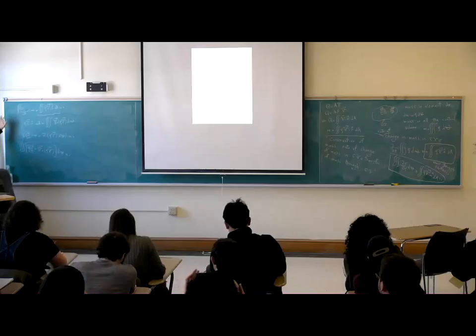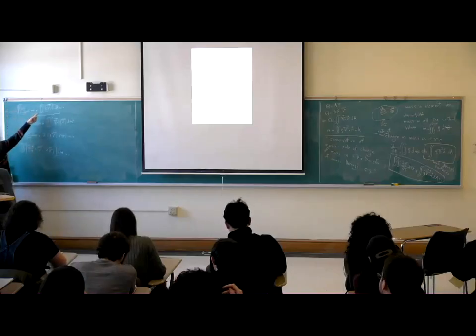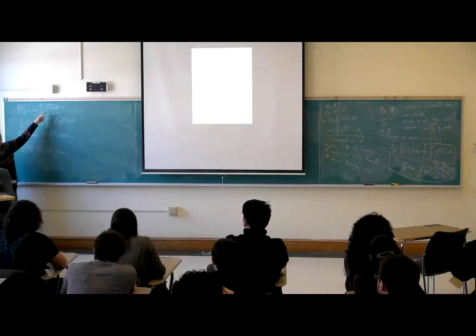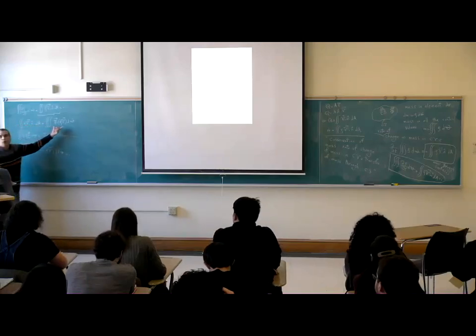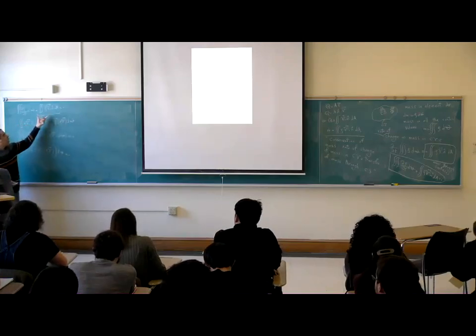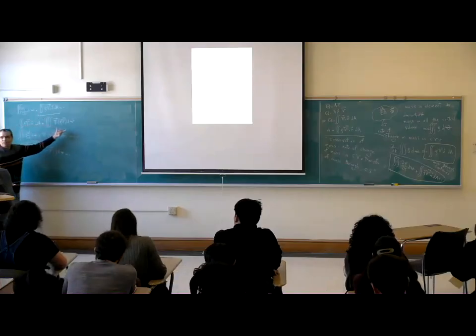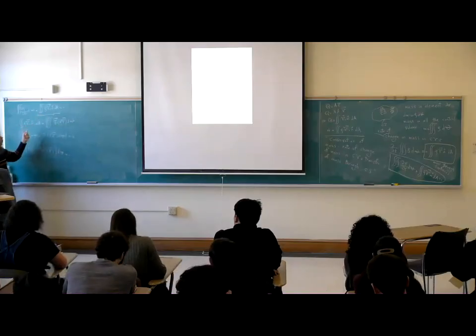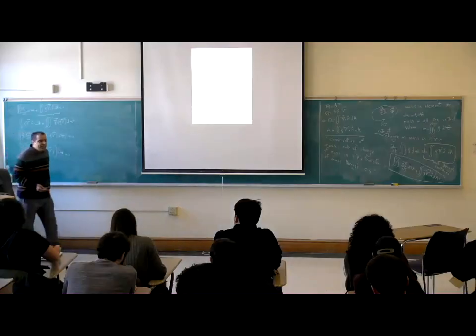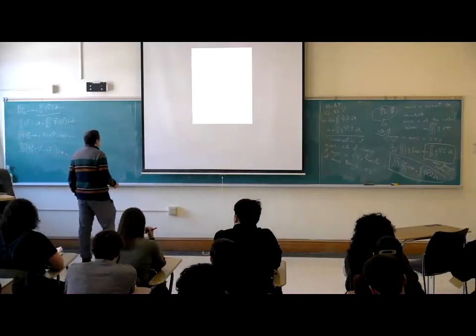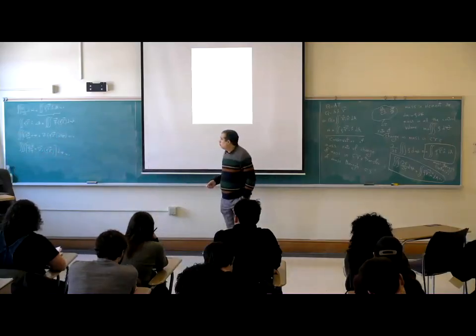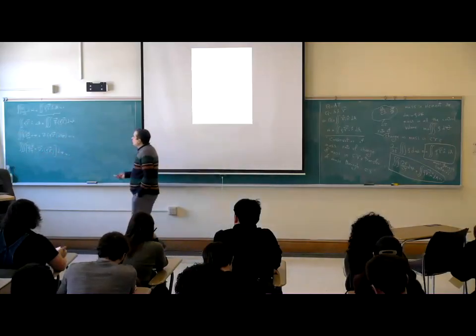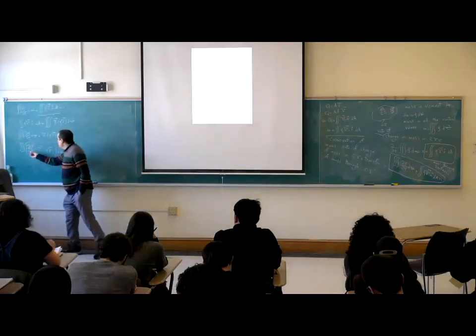Okay, what did I do? I wrote this equation, the continuity equation. The surface integral can be converted to a volume integral. I converted the surface integral to a volume integral: rho v dot n dA is equal to divergence of rho v d volume. So both integrals are now with respect to volume. I write this.